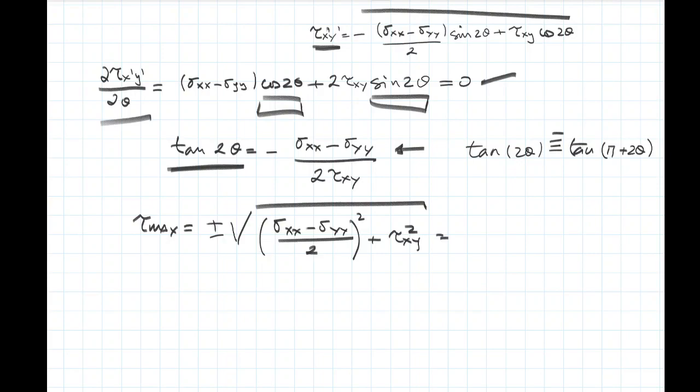But this is just to say that, after a few substitutions seeing what is inside of that, this is going to be equal to 1/2 of the subtraction of the two principal stresses found before. And this is totally aligned with what Mohr's circle has to say regarding the value of this. So this is in fact the radius of the Mohr's circle.